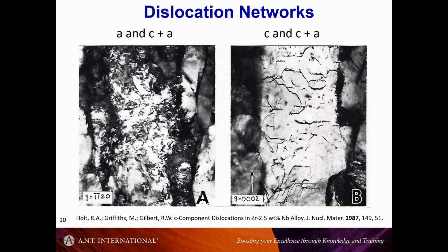In the austenitic alloys, and I'll talk about dislocations later, there's only one type of glissile dislocation, the half <110> type dislocation, which is simply the shortest interatomic distance of the atomic lattice. But in hexagonals, there are some peculiarities, and you can get this mixture of dislocations.